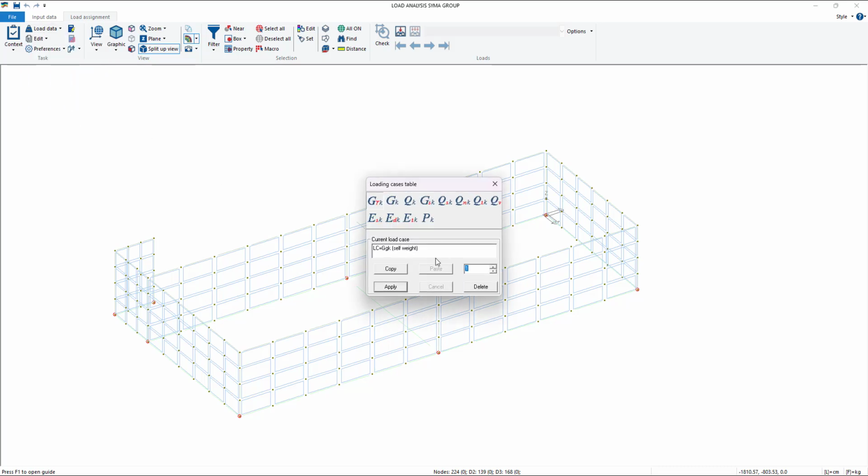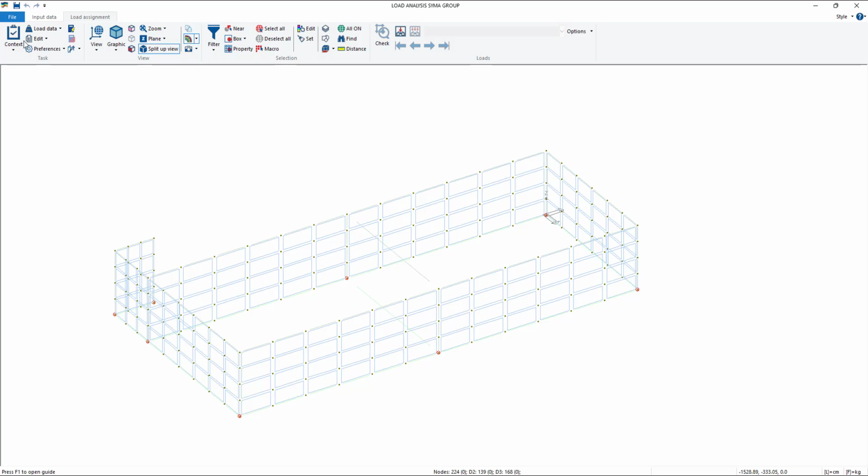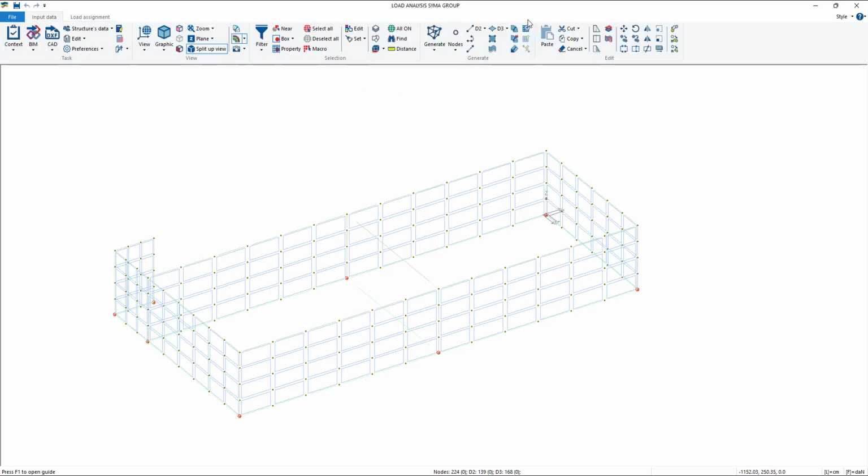If we go on load cases, we can see we have the self weight, and then we have the seismic dynamic. To have the variable weights like that, we have to model some horizontal plane elements. So slabs, I mean, the correct term is floor panel. These elements trigger the auto definition of the variable weight.